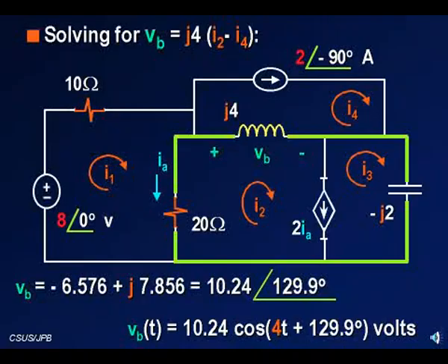Now, this is another thing you're going to have to get used to here, is that when we calculate values, remember phasors is a method for solving circuits. So we typically have to write the response in rectangular form and in polar form, because the polar form is the one that is needed to go to the time domain form. The function in time domain is the solution, not the phasor function. So the phasor is only a way to get to that function. So the final result should usually be in the time domain if you were given a time domain function as inputs, essentially.